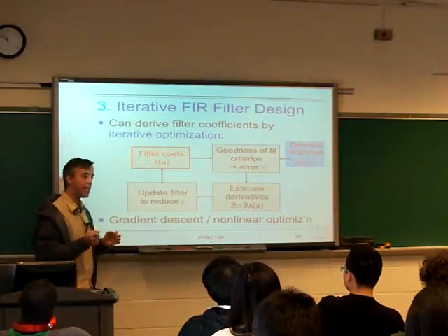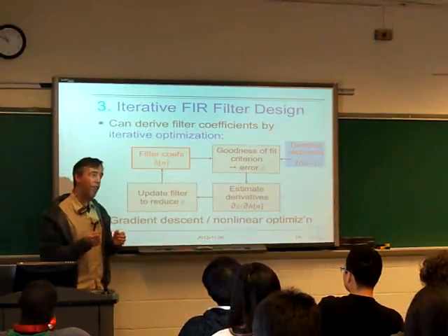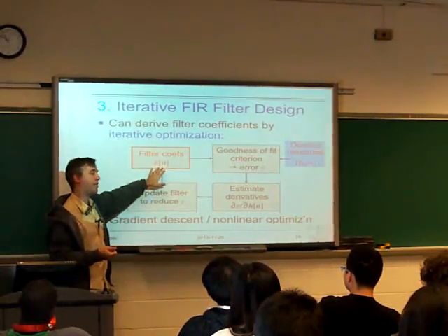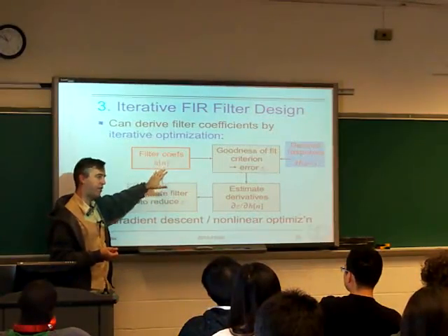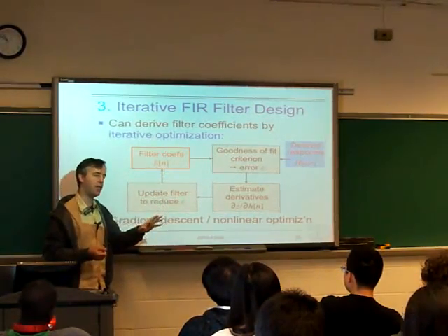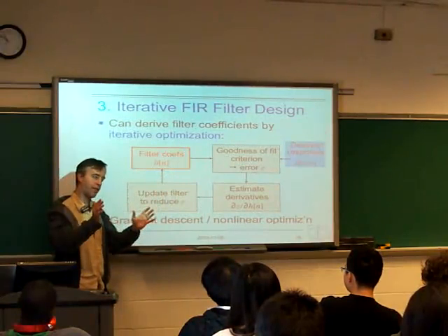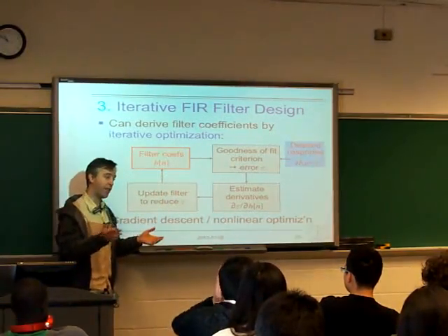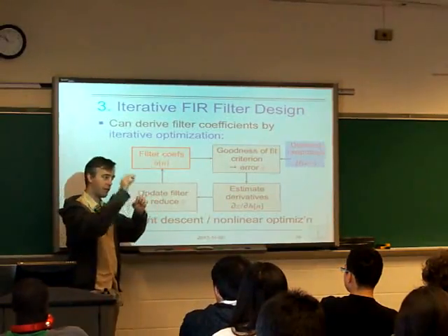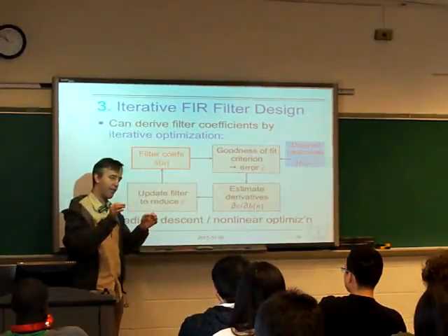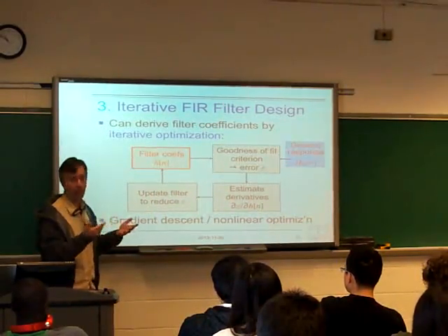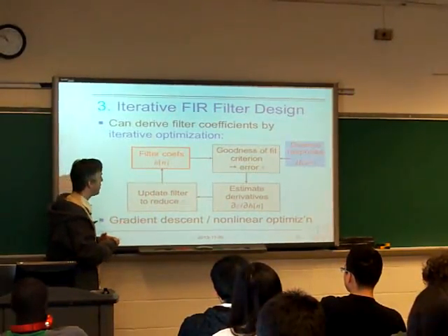And the reason this is a nice problem for this kind of technique is that we've got this finite description of the filter. The filter is going to be some set of values in this finite dimensional space, the number of the length of the FIR filter, 25 points or whatever. There's going to be this 25-dimensional space, which is all possible settings of those 25 values, and then one of those is going to have the best properties according to whatever criteria we want to optimize.